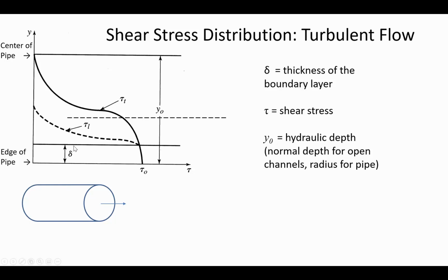And so this boundary layer thickness is something that we want to be able to estimate because it's important for us to be able to compare the thickness of that boundary layer to the roughness elements that the pipe is made out of. Remember that if we zoom in on a pipe, we're going to find little irregularities, and it's going to look like mountain peaks, where even something like a steel pipe, which if you run your fingers across a steel pipe, it feels smooth enough.